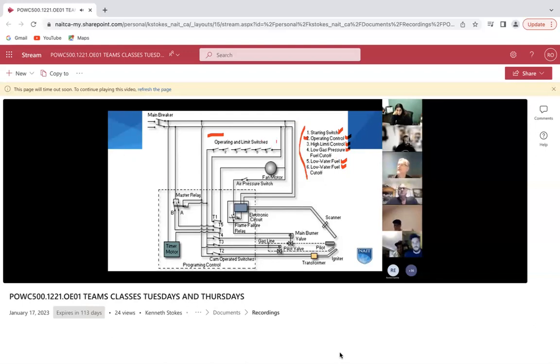And if you look at the list and then glance over here, you'll see a bunch of open switches. The open switch is signified by a little line where it's not connecting the other line. So unless all 6 limit switches are closed, we won't have any power to this system.